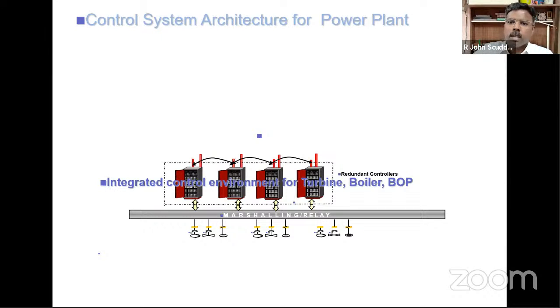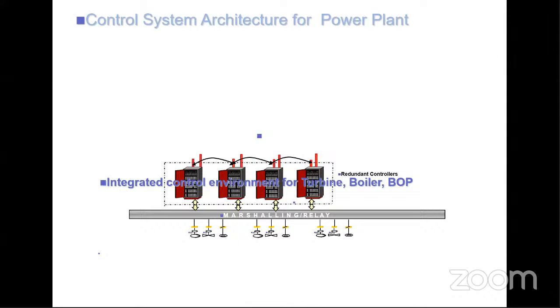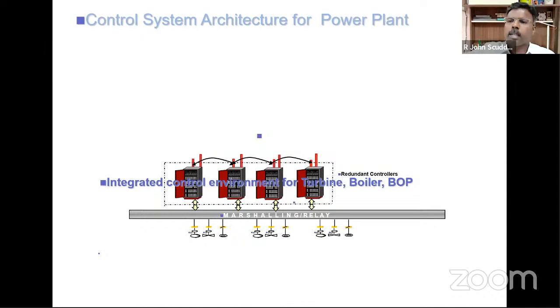And from one junction box, we have a big cable, which is maybe 32 or 64 cores. It can carry 64 signals, or at least 32 signals at a time. It will bring it to the marshalling box. From there, you are again taking it to the DCS nodes. Now these modules are getting individual inputs in individual wires. Whether it is coming in a big cable which can carry many signals, or from an independent cable from the field, it is coming to the control room as a signal.